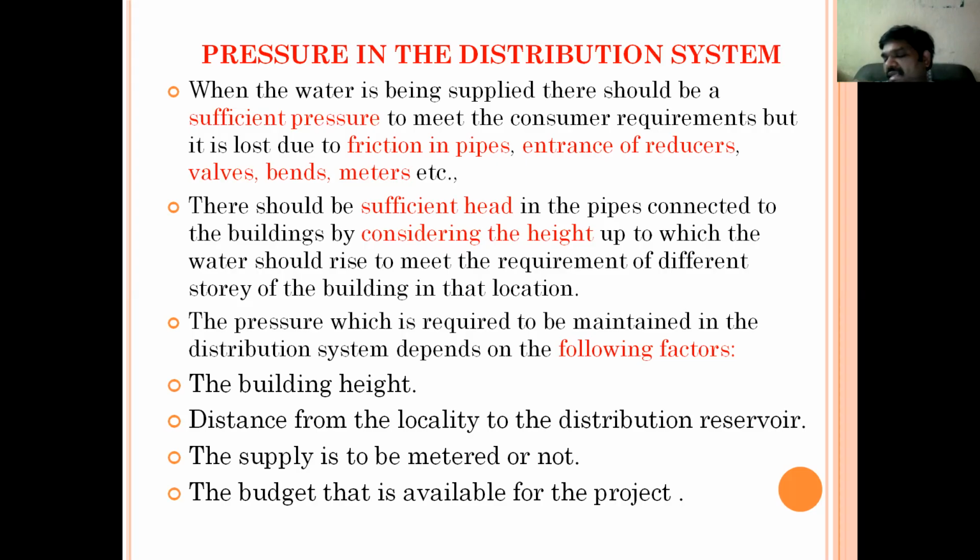In the same way, sufficient head has to be maintained. See, if the sufficient head is not maintained in the pipelines, supplying water to high-rise buildings is somewhat difficult.